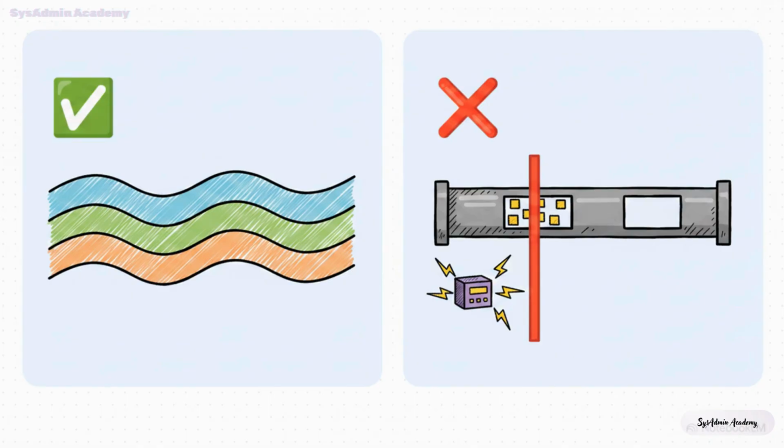FDM is inflexible. The number of subchannels is predetermined, and adding more usually means you need entirely new multiplexing hardware. Plus, frequency is a very scarce resource. A radio station might broadcast 24/7, but data communications are often really bursty. If a device has a dedicated frequency channel but goes idle for a few minutes, that frequency slot just sits there, completely unused. It can't be dynamically shared with another device that might be desperately trying to send data.